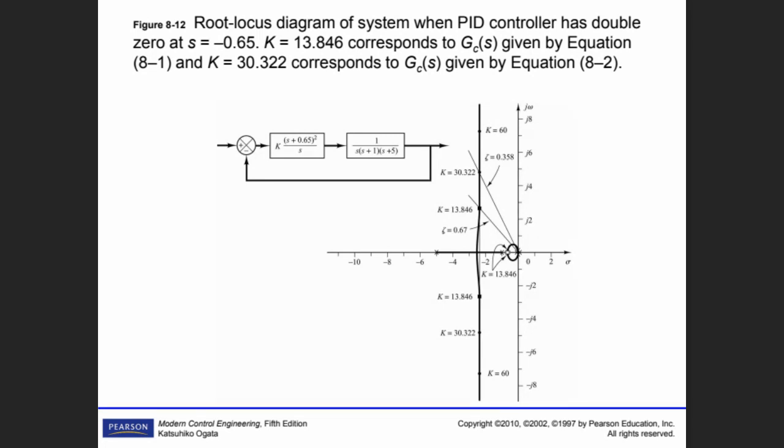Of course, you directly put, let me enlarge it a bit. You directly give 0 here. What's happening? One of the S here is already over there. One of the S I added with PID. I have two S's. So 2S is moving like this. And then, of course, we have two zeros here. Two zeros just couple with these two zeros, the two origins, and then two poles here, and two zeros here.